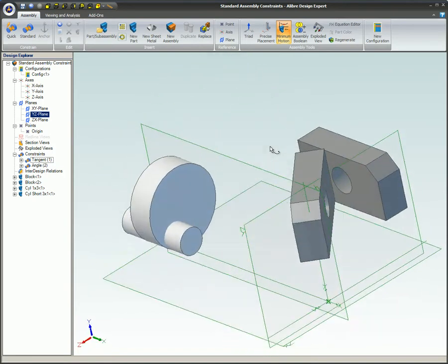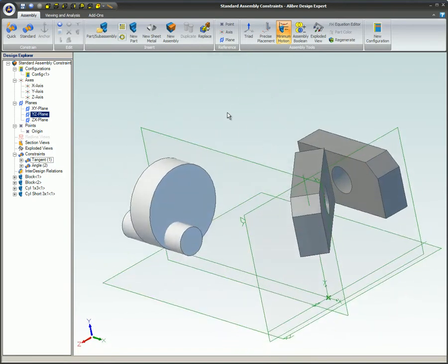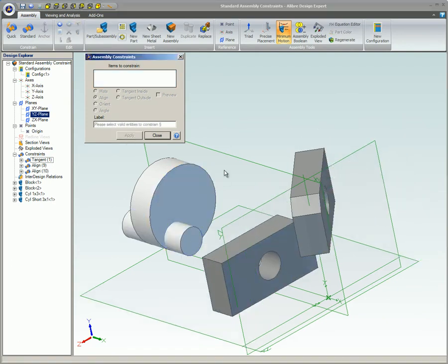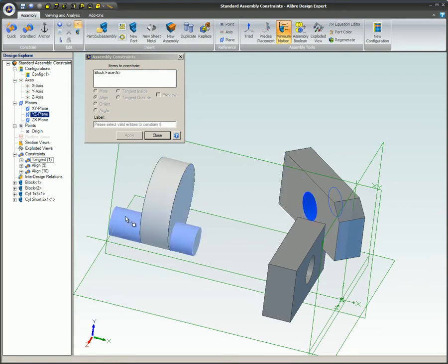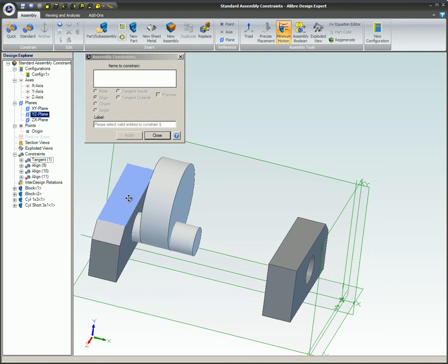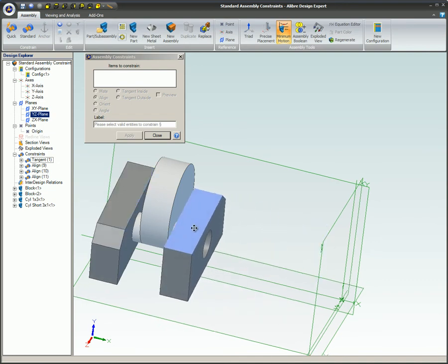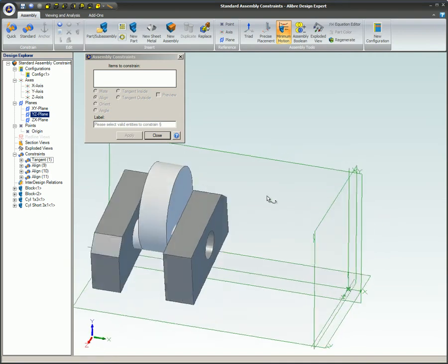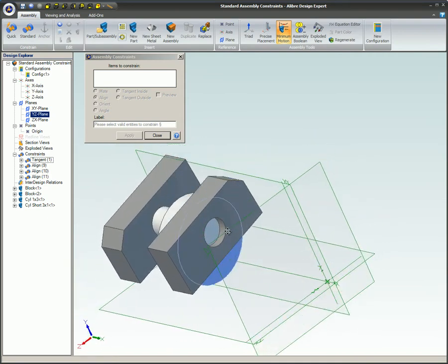This video was an assembly constraint overview. Assembly constraints allow you to build an assembly prototype by constraining the individual parts together. It typically takes a combination of 3 constraints to fully constrain a part so it is not able to move or rotate. Constraints can be applied to planar faces, edges of parts, cylindrical or linear, vertices, axes, and planes.